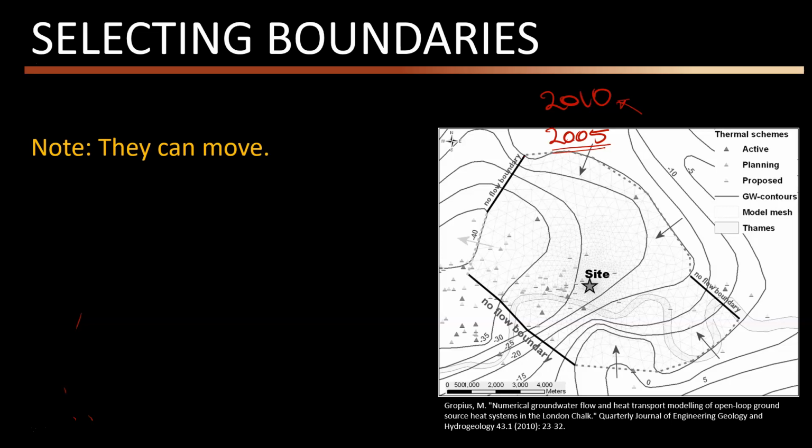But there are so many cases in which, if you study multiple potentiometric maps in different years, and I'm going to show it later in the next slide, you see that they are reasonably located in similar places, so that you can make an average of these no flow boundary conditions and define a proper boundary condition which represents the average condition of these 15 years.